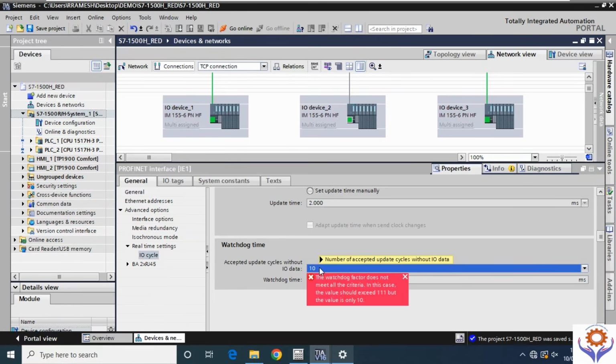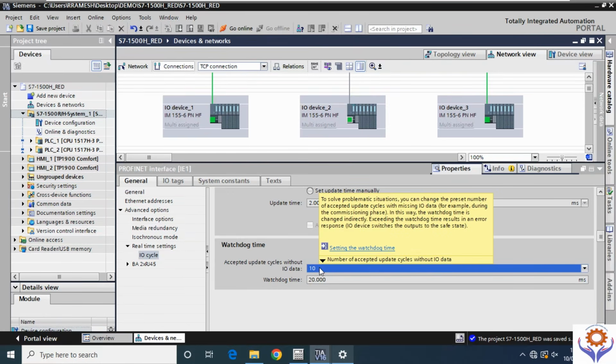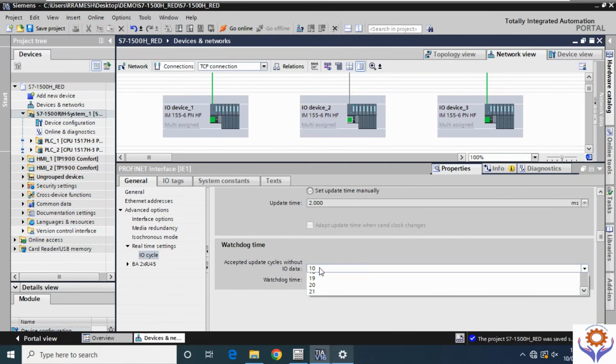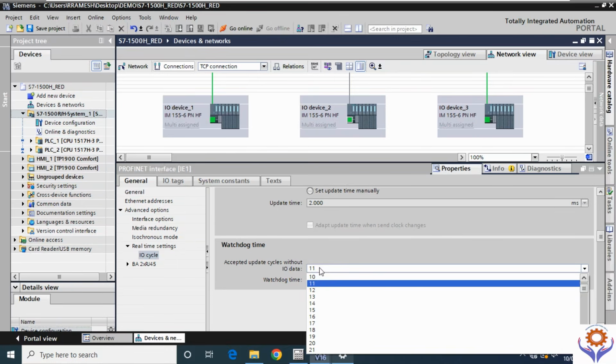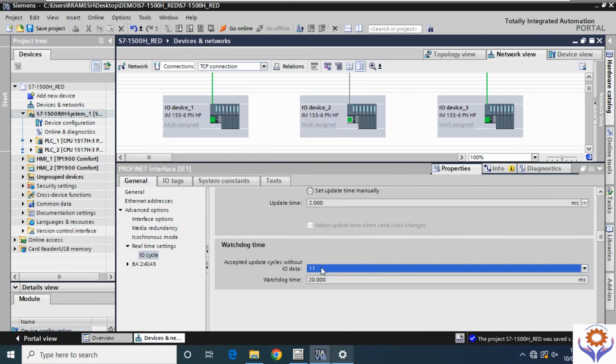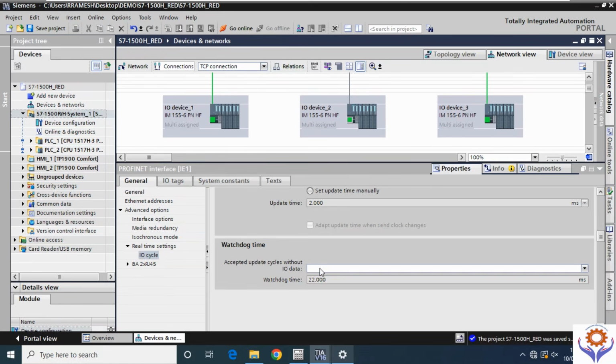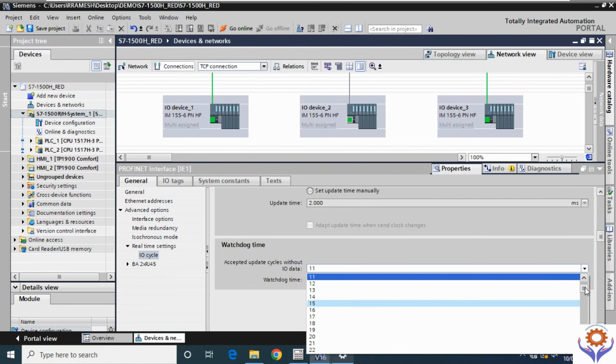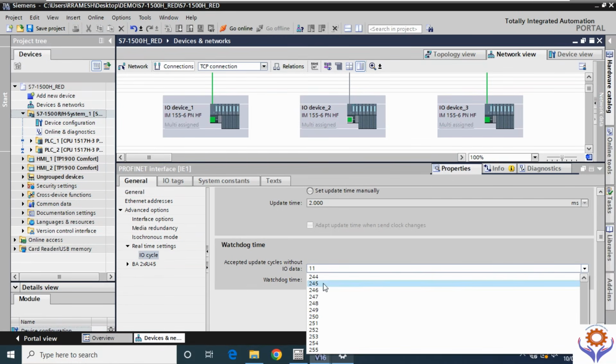So you can find this detail, for example the Profinet speed. This is for the real-time settings for IO cycles. So you have to change this one. If you see on the right side, you can drag and drop. You can select a range more than that. See here. See now it's not showing any error. I'm just saving the application again.